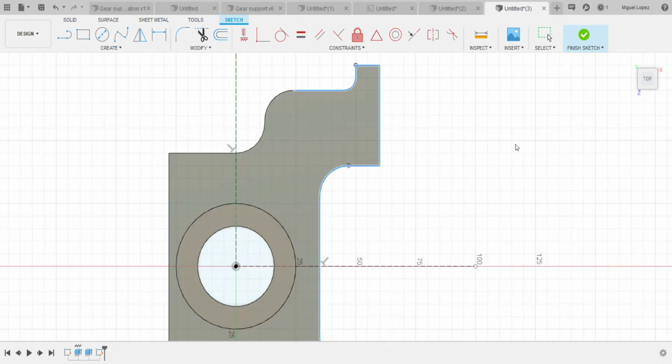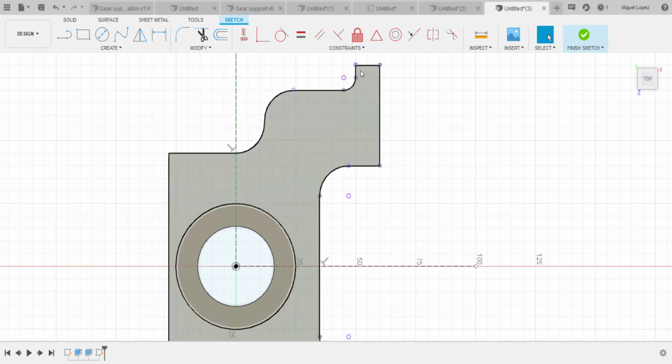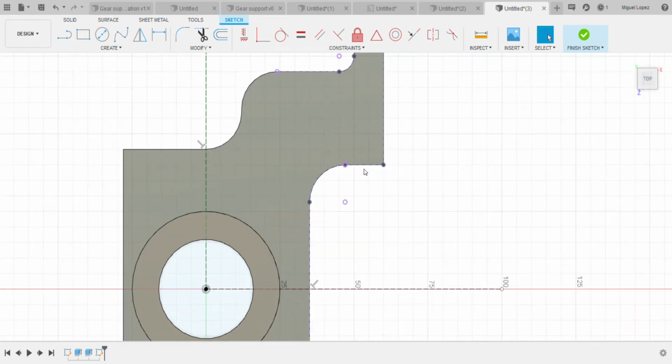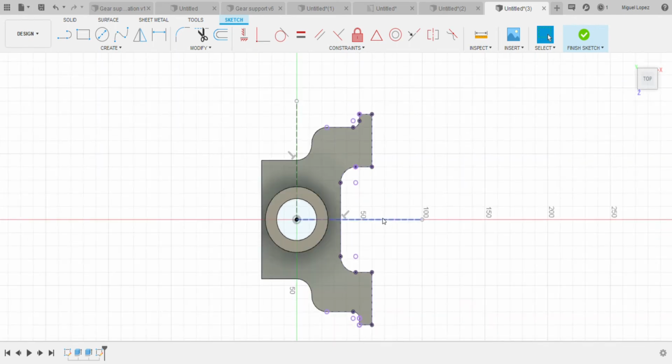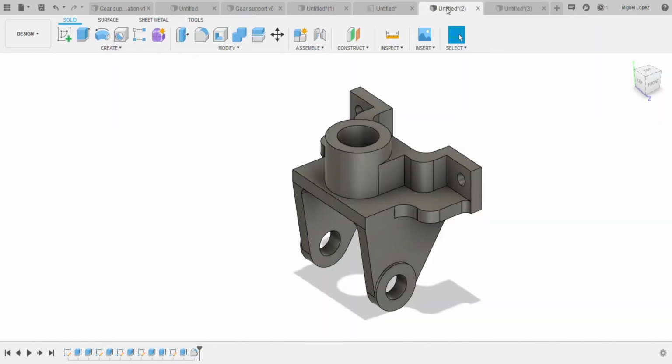So I'm just selecting the bottom part of it. Okay. Then you click on OK. So as you can see, these lines are available if you want to not draw it again or whatever. You just project them. Now here, where we're gonna create is just this section over here, and then extrude it.